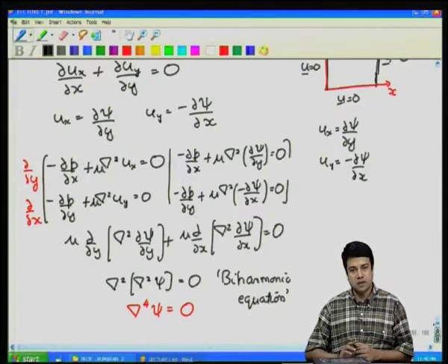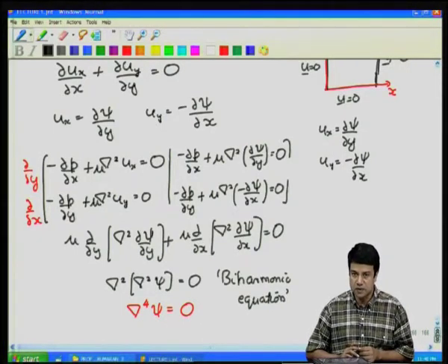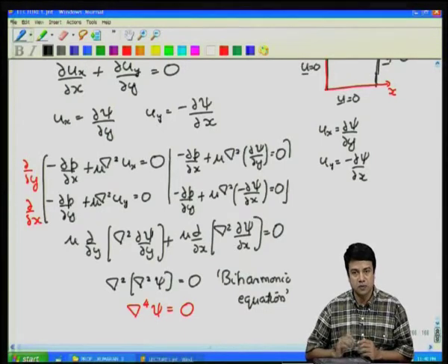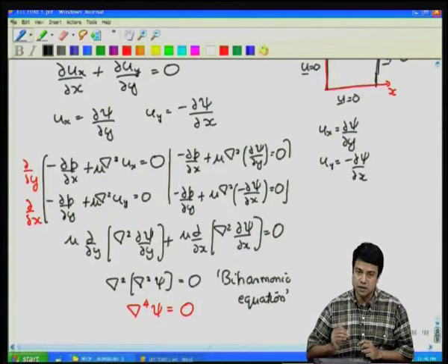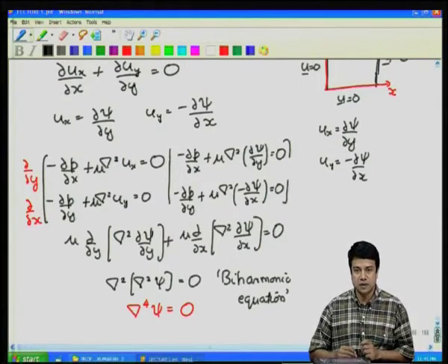Of course, in Cartesian coordinates, the way to solve a Laplace equation we saw earlier when we did heat and mass transfer. You take partial x square plus partial y square of the temperature equal to 0, identify the homogeneous boundary conditions, you get an eigenvalue problem in those 2 boundaries, and then the other 2 boundaries have an inhomogeneous term, and the constants in that are determined from orthogonality relations for the eigenfunctions obtained in the eigenvalue problem. Okay.